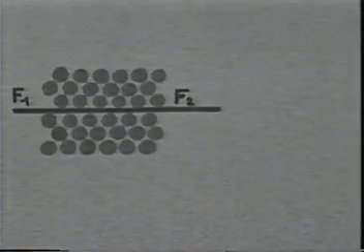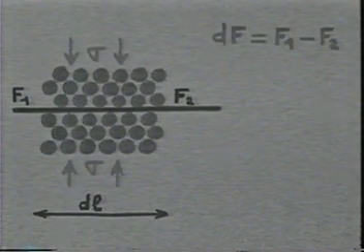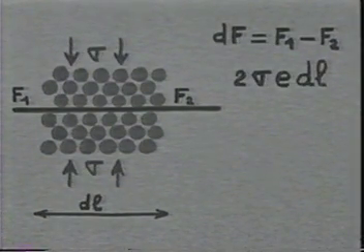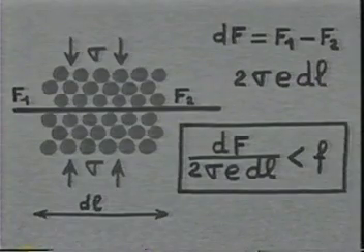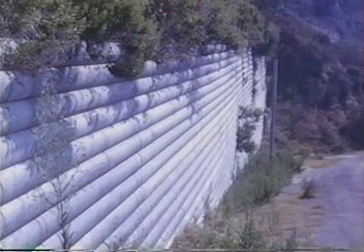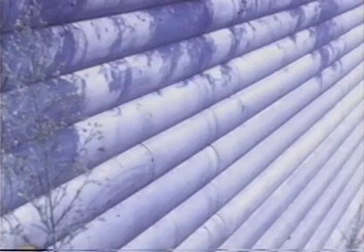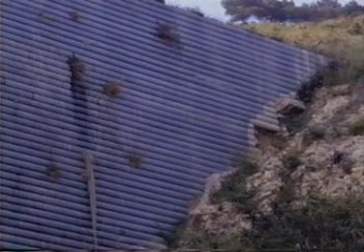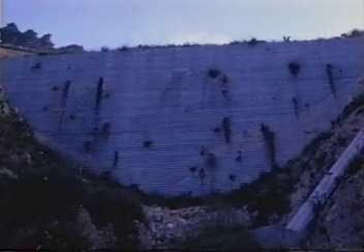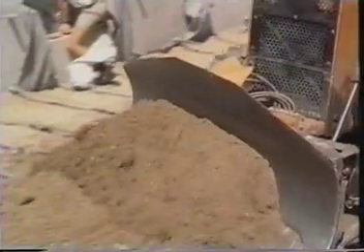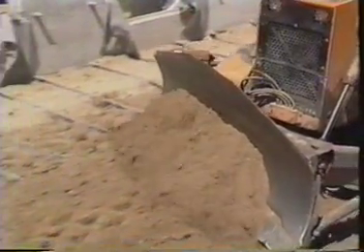With friction as the principle, Vidal developed the design concepts for what he called terre armée, or reinforced earth. His prototype reinforced soil wall was constructed in 1964, using steel strips to reinforce selected fill. 4 years later, this system was used to construct a major wall on the Autoroute de Menton in France. This particular system comprises 3 elements: selected fill, steel soil reinforcing strips, and semi-elliptical steel facing units.